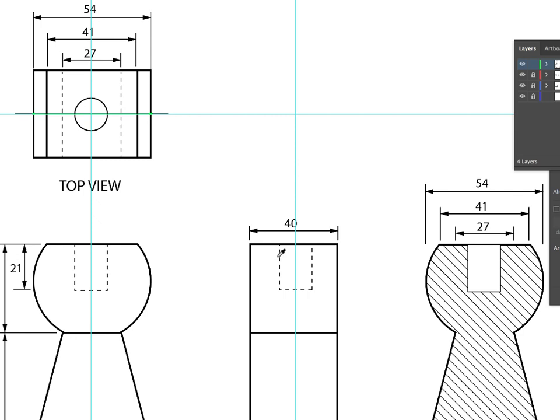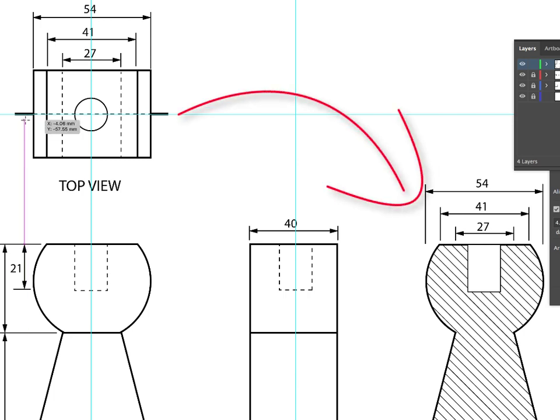We can just copy an existing dashed line that we already have. And finally, we can select the lines on the outside of the object. Holding the Shift key, you can select both those segments and then just go up to 3 point on the stroke size. We are now ready to place the arrows to indicate just which direction we're facing the cross section.